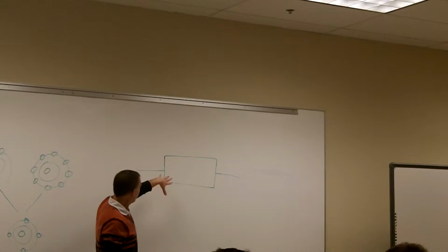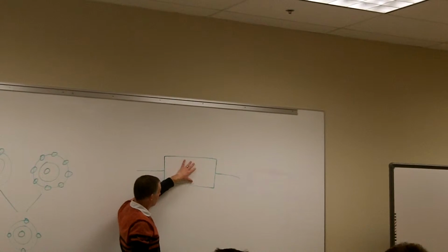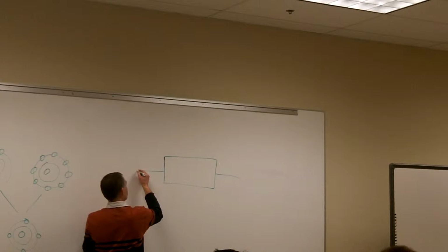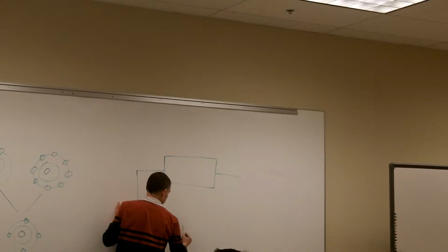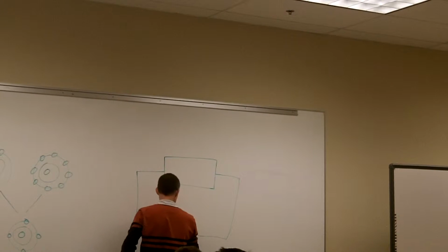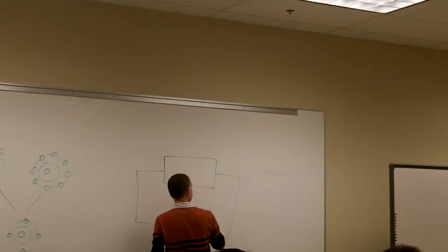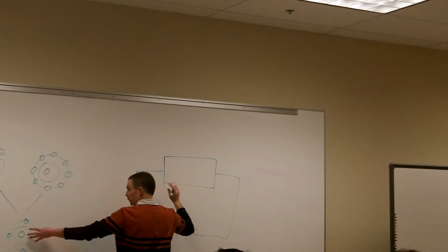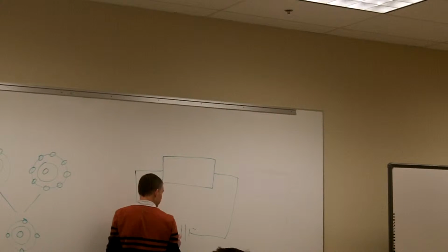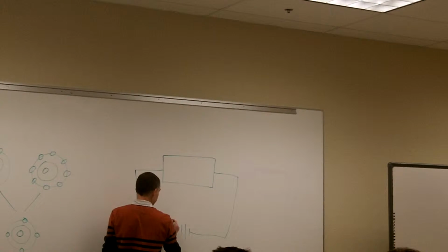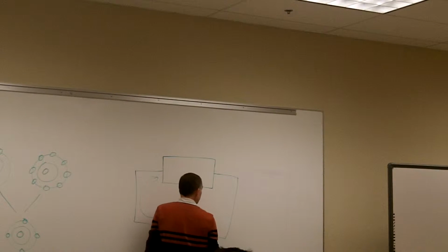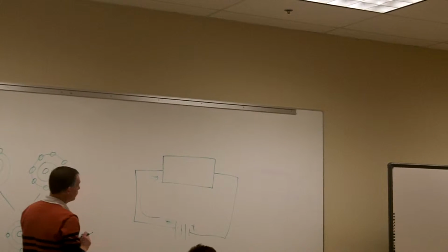If I make this diode just out of silicon, and I put a voltage into it, negative, positive, I'm going to get current to flow. I'm going to get enough voltage to get these free electrons to start moving through there. I can get the current to flow this way if I have my polarity that way, but if I switch my polarities around, I can also get my current to flow the other way through it. So that wouldn't do us any good.